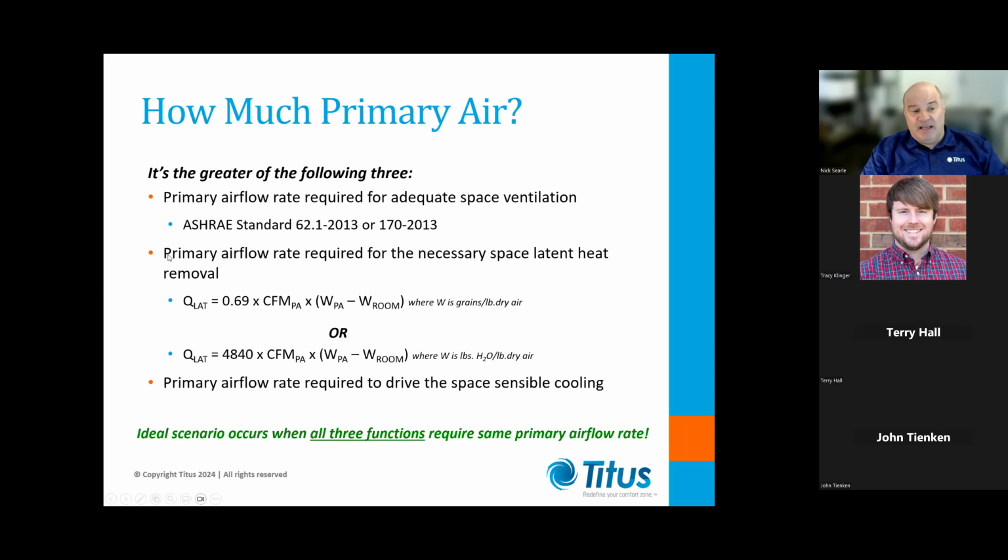So if you maybe need 0.25 to 0.3 CFM a square foot for your latent cooling, you may need sort of 0.4, 0.5 CFM a square foot if your loads are extremely high. But again, still, you're getting a huge reduction compared to conventional VAV. But the reason this is an important point is because it may dictate the type of air handling unit that you use. So you may be forced on the perimeter of the building to either over-ventilate if you're using a DOAS air handling unit, or what most engineers do is use a recirculation air handling unit, so they don't go DOAS at all on the perimeter.